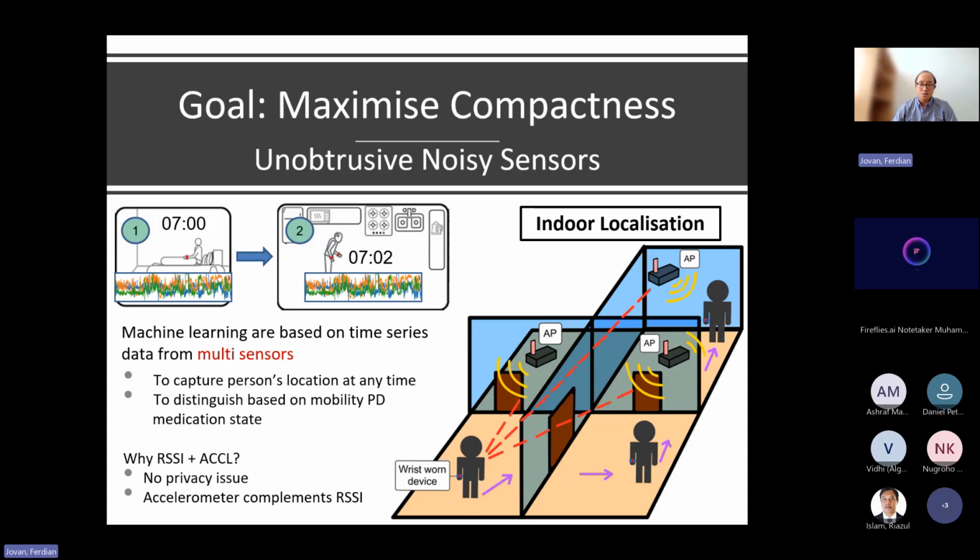We don't have the gyroscope because it takes too much energy, so this in-house wearable can only last for 1 day. They would need to be recharged every day, which is not good. So we are left with the second option: continuously monitor the location of the person using RSSI and accelerometer.